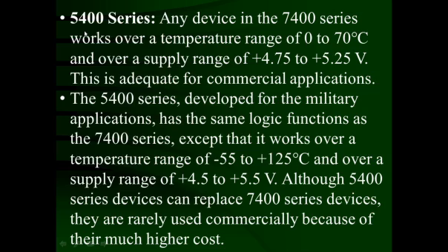For that, another series was developed, known as the 5400 series, for military application. Devices in the 7400 series work over a temperature range of 0 to 70 degrees Celsius and over a supply range of plus 4.75 volt to 5.25 volt. So it requires 5 volt, but a variation of plus minus 0.25 volt is tolerable. For 7400, the commercial application ICs, this is adequate.